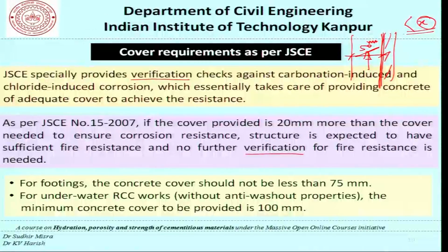And now, in order that the chloride concentration at the surface of this reinforcing bar is less than X, we need to put in place a certain cover and also a certain type of concrete. Now, based on a model which talks in terms of the diffusion of chlorides into this concrete, it can be verified if the concentration at the reinforcing bar location at the end of service life should be less than this X. So, we are not getting into the modeling of that, but that is the verification statement being made.